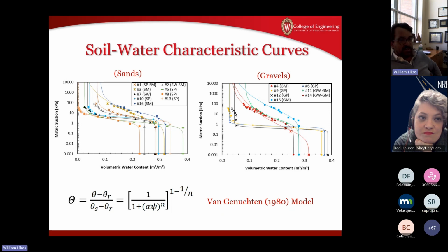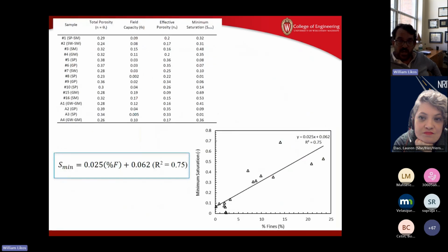Yeah, so we didn't measure Atterberg limits. We simply measured percent fines from sieve analysis. It's a really good thought, though. I wouldn't be surprised if there is some normalization that could be done. For example, percent fines that contain a high plasticity clay are going to retain more water than the same percent fines of a lower plasticity clay. We didn't look at that, but that would definitely be a way to refine this correlation.